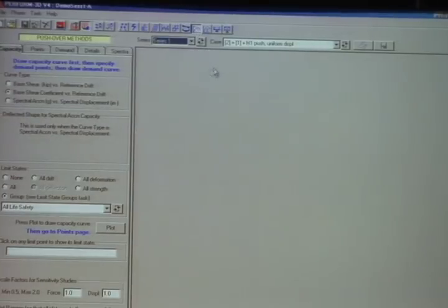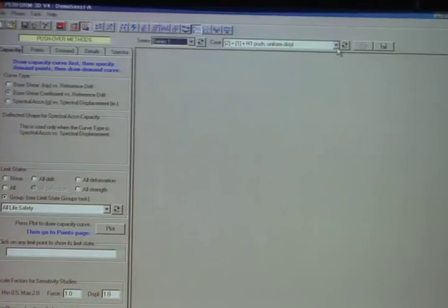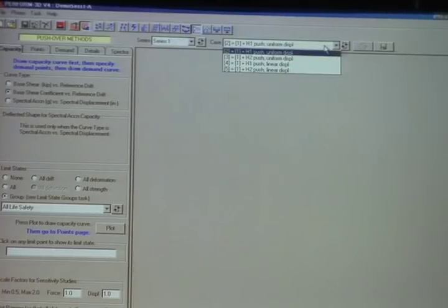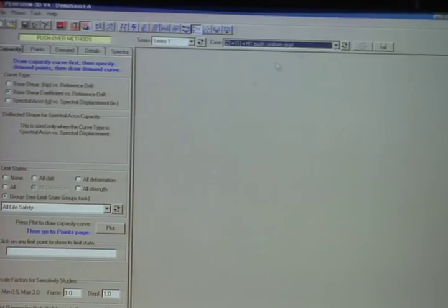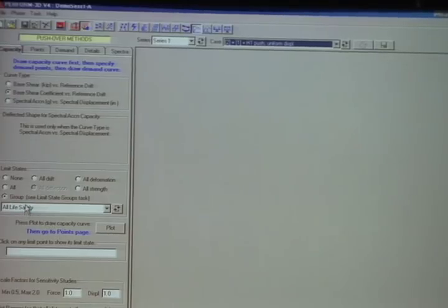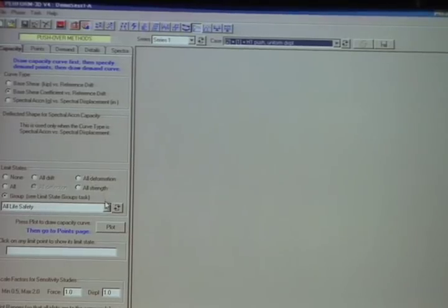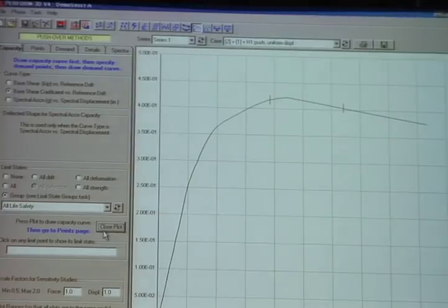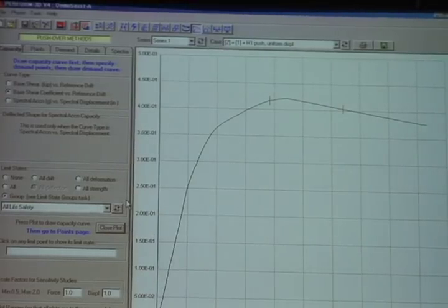That was earthquakes. And this is now, it's going to be horizontal, the push in the horizontal one direction, and it's a uniform pushover. And there are 4 different pushover analyses here. I'll just look at one of them. And I'm going to, first of all, plot the pushover curve. And this is what it looks like. And there's some P delta effect, so there's some loss, strength loss as it gets into the buckling range.